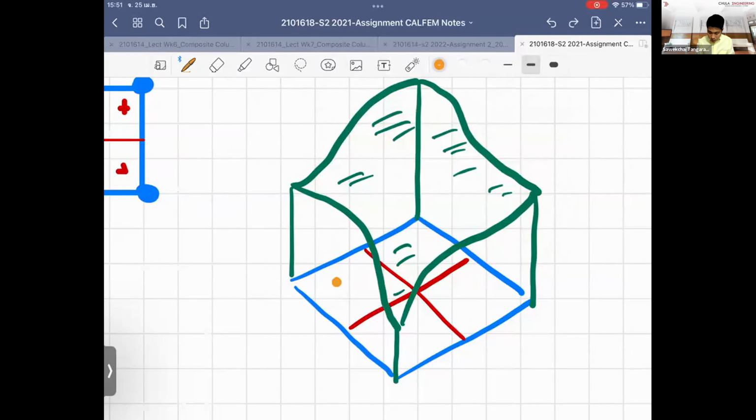This is my Gauss point here. So what happens is we project the stress up to the line of the surface. And then they're saying that the whole block of the quarter area that we're looking at takes the value of the average stress in this area.